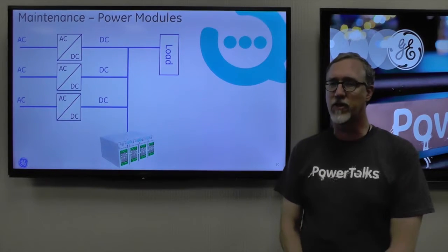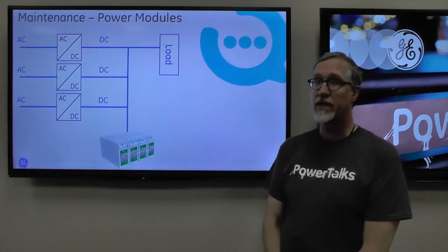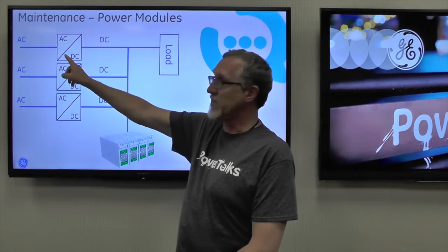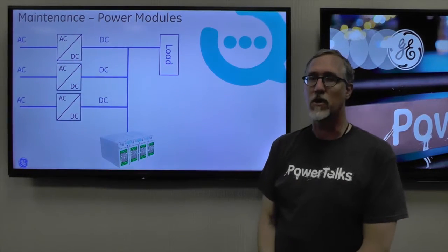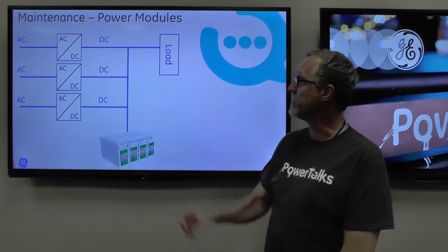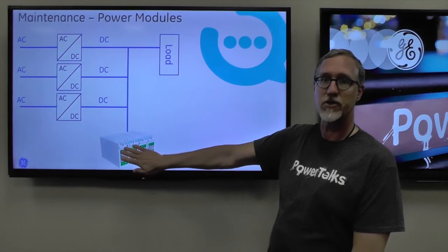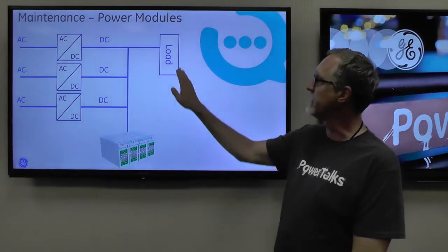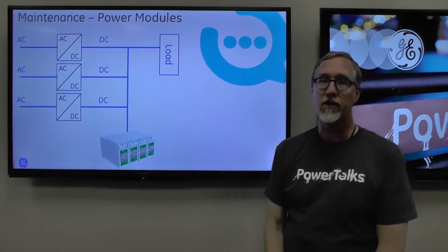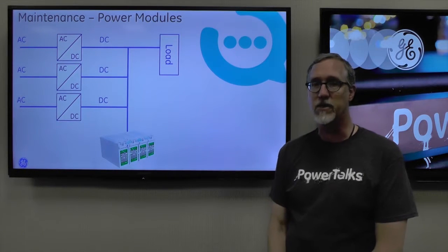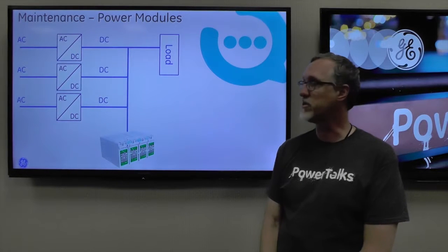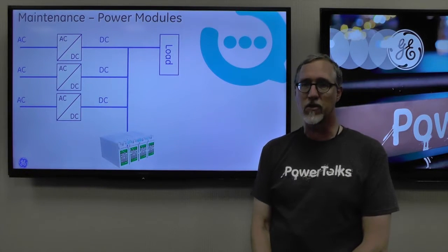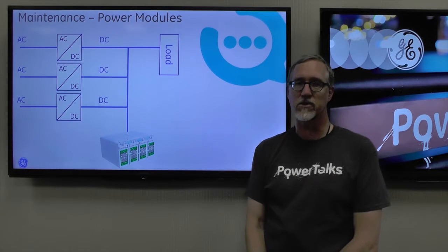This is the typical configuration for a high reliability DC power system. AC is converted to DC in what is called a rectifier module and used to directly power the loads and charge the batteries. Because the load is directly connected to the battery, even if the rectifier fails or the AC power fails, the load is still supported by the battery, and there is nothing between battery and the load to go wrong except mechanical connections.